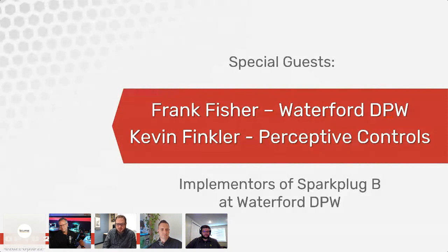But going through, we started testing. We got a couple controllers to test, and then we decided to try a couple of stations with it, and it worked great. And the biggest thing for us is we had a polling program that would take four or five minutes to pull through all of our sites. Well, with MQTT, we're instantly getting that data back, with our cell modems.